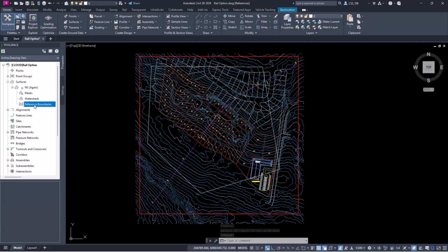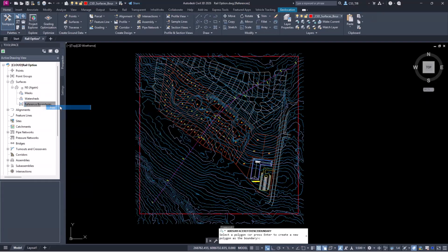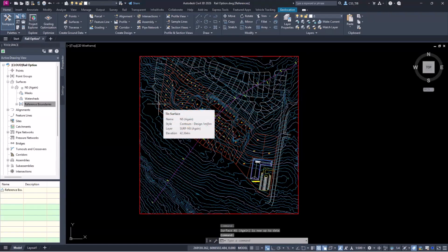And then if I actually didn't want to do this at the time of creation and wanted to do it after I'd already made the surface connection and decided I wanted it smaller, get rid of that one. I can actually use, say, this red polyline here and come in and add that. I could pick it second and refresh the connection and it trims down. So quite handy when you're using those data shortcutted surfaces just to be able to take parts of a terrain into a separate project. All right.